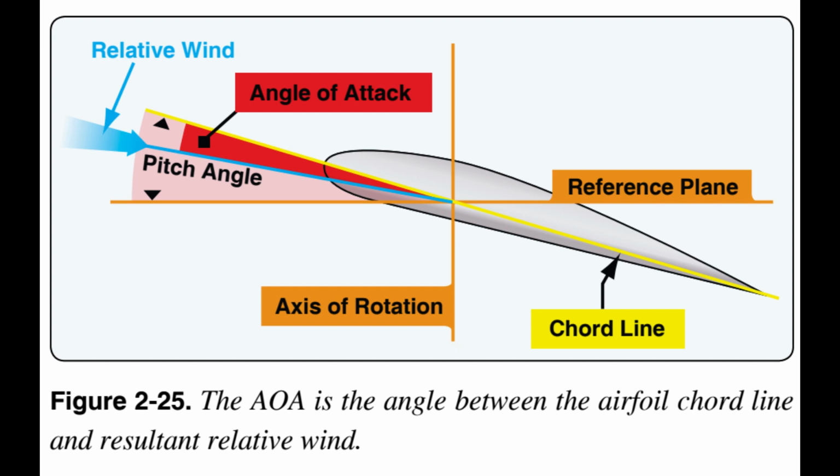The turbulence results in a large increase in drag and loss of lift in the area where it is taking place. Increasing the AOA increases lift until the critical angle of attack is reached. Any increase in the AOA beyond this point produces a stall and a rapid decrease in lift. Refer to the low rotor RPM and rotor stall section of Chapter 11, Helicopter Emergencies and Hazards.